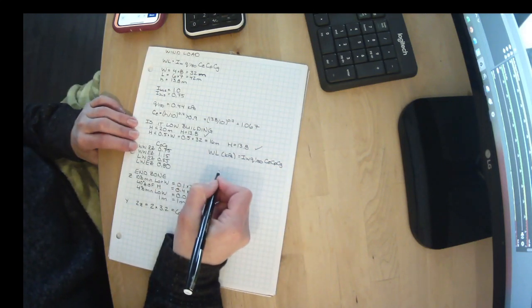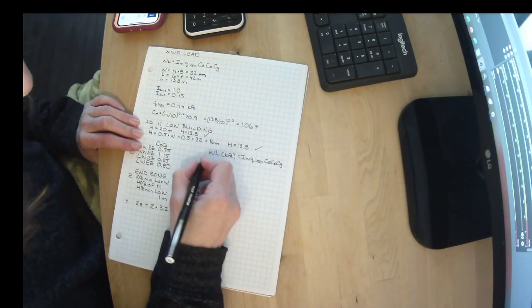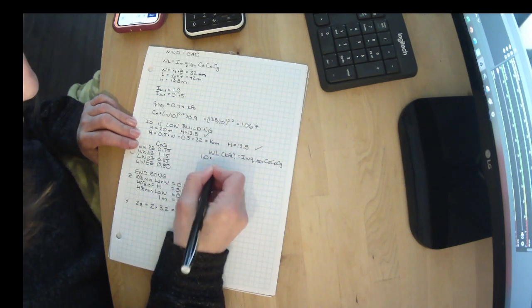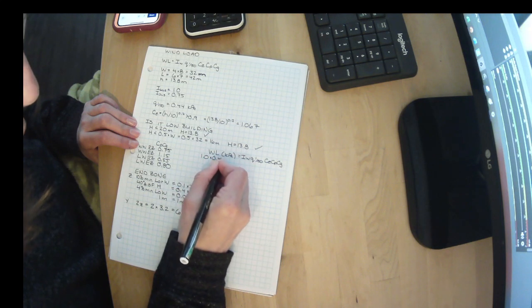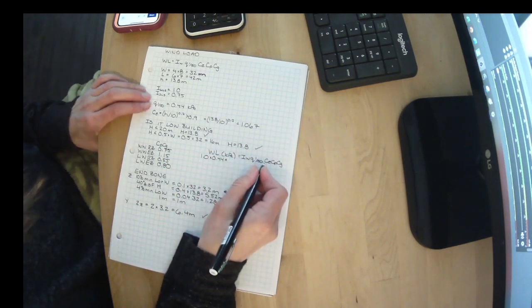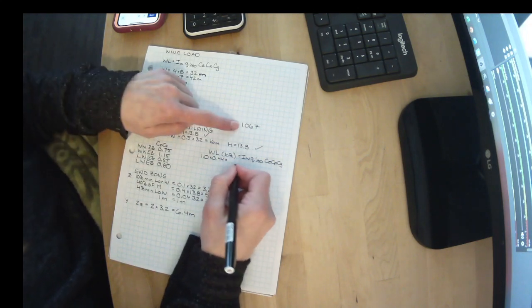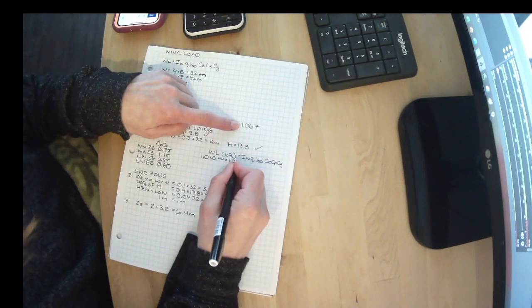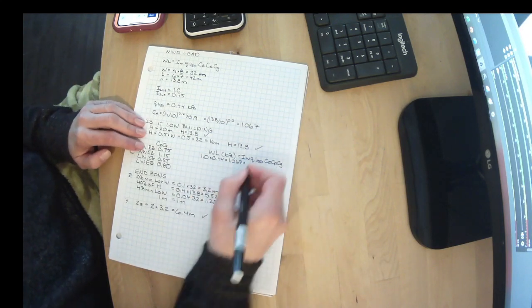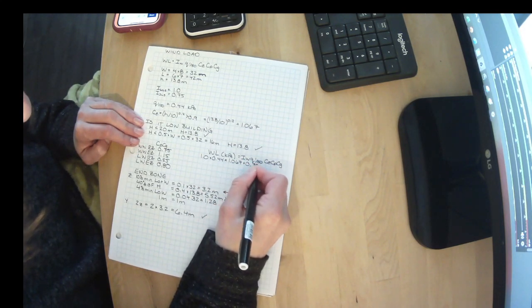So for our windward regular zone, we have 1.0 times 0.44 times our CE, which we calculated as 1.067, times CpCg, which is 0.75.